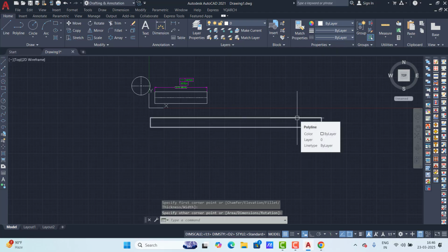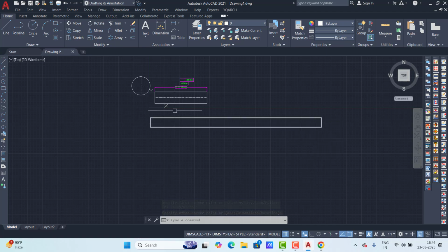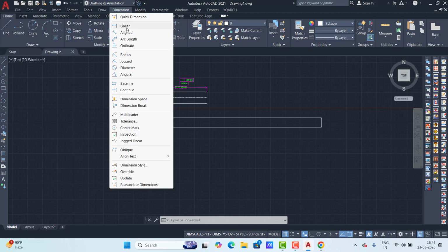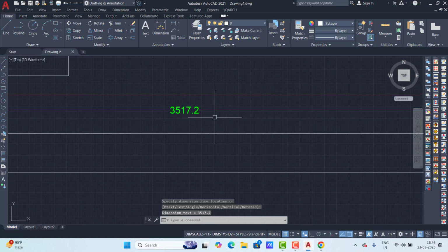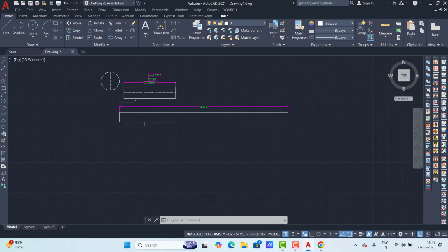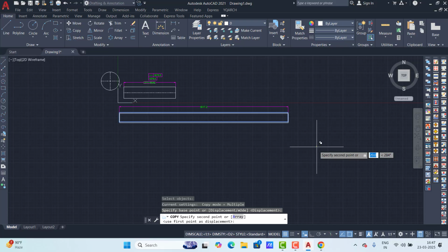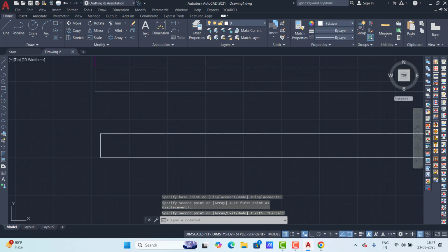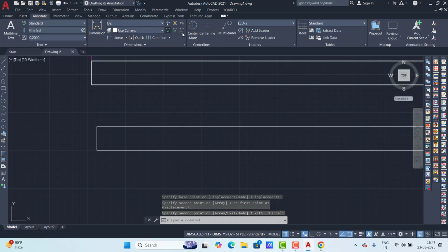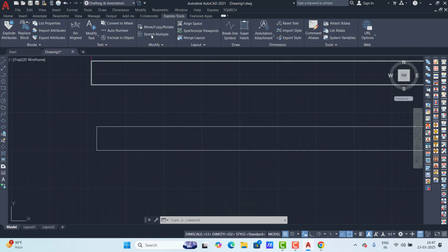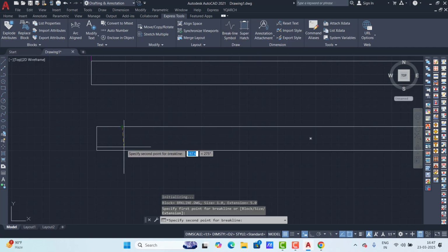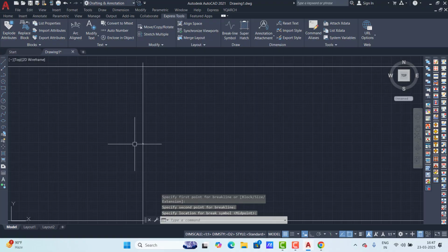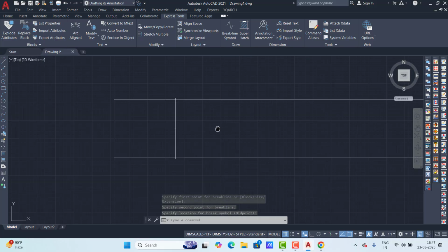So when you use an iso circle in isometric and you use the radius option, it does not show, because this is not a true circle. So here we use only the multi-leader option. Okay. So with the multi-leader option you click this way, click here and type the value, for example R and then 20 or 50. This way type. Okay. Now by default this setting comes. So in isometric, this one I have taken as 400. When you use the linear option, you see that the dimension is not correct, 364 coming horizontally and vertically. So the value is not correct.